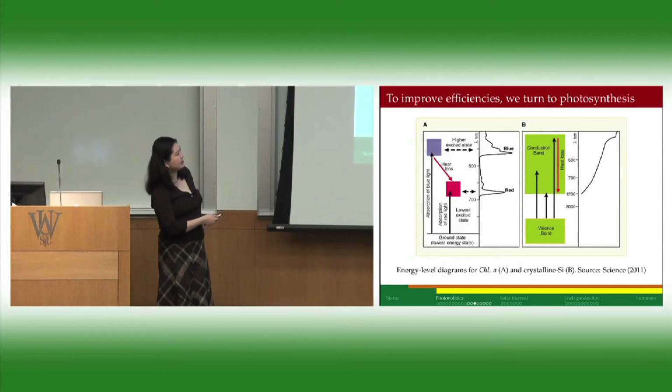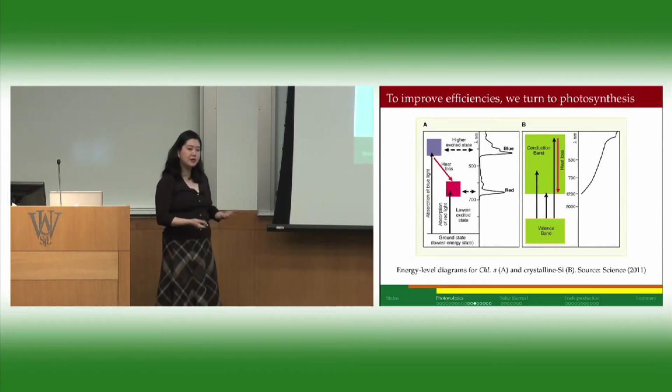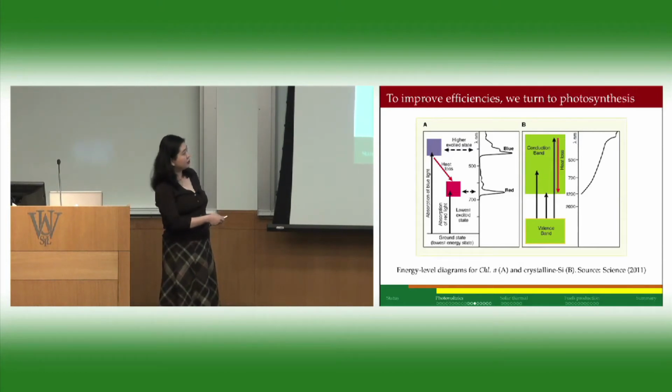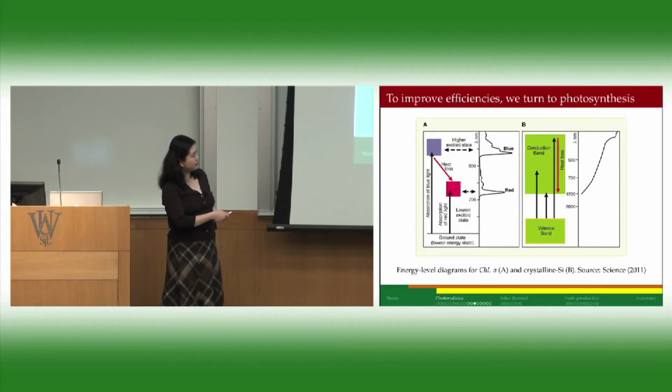And in the semiconductor that we already know about, if somehow your incident photon gets you just over this bridge to the conduction band, then you're pretty efficient and you're pretty happy here. However, if the photon energy is too high, you actually lose a lot of this energy to heat. So that's where some of the inefficiencies lie: your electrons are too excited, and they end up having to decay back down to the first excited state. This is where a lot of your inefficiencies are.